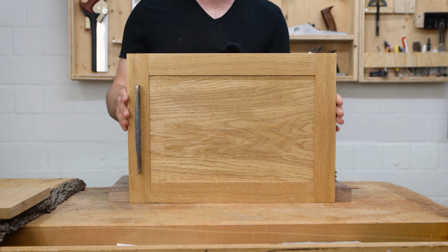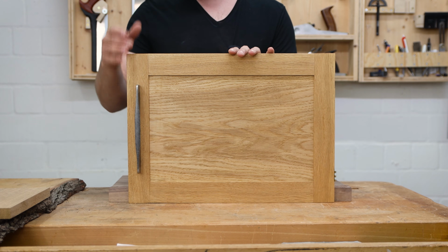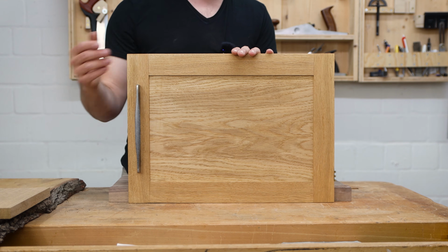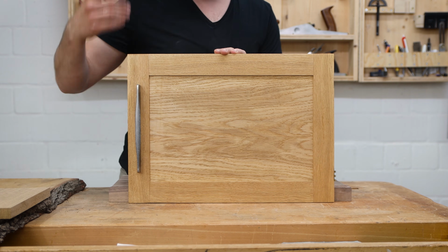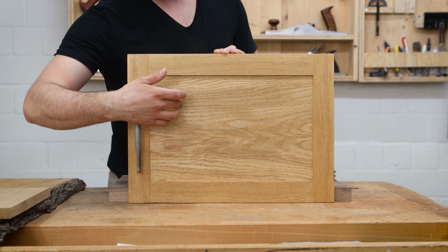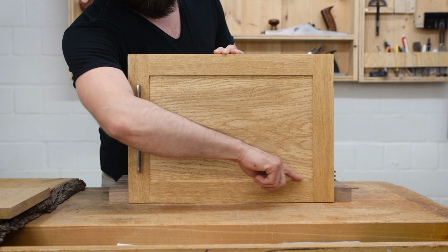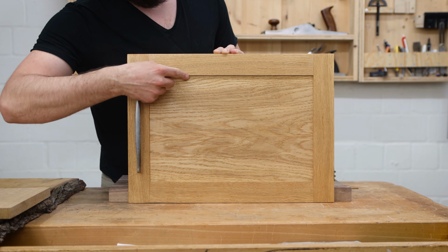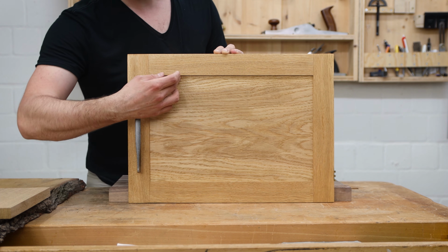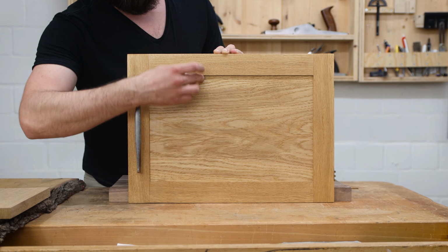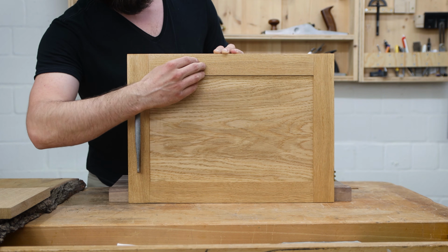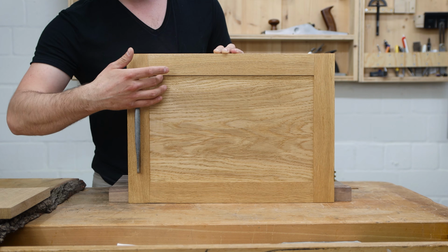Have you ever wondered why so many doors and drawer fronts look like this, with a frame and a panel in the center? It's because of wood movement. You have these rails and stiles around it, and then you have the panel in the center. The panel in the center is only glued into the groove on one side. And the groove on the top here is actually deeper than the panel goes, because then the panel moves across it with the most and can expand into the groove even further and contract in the groove, so you won't actually see it.